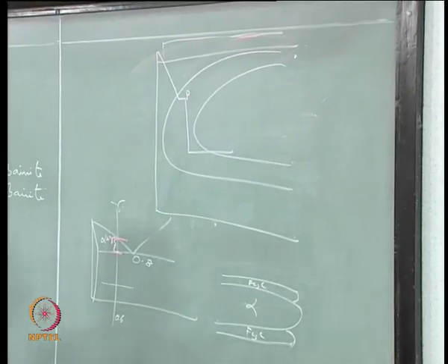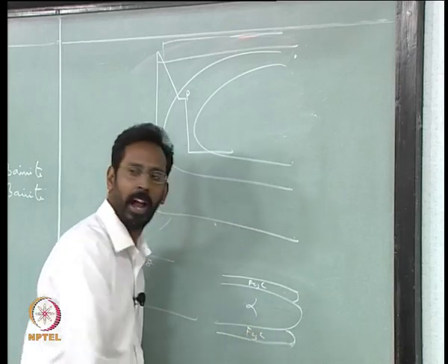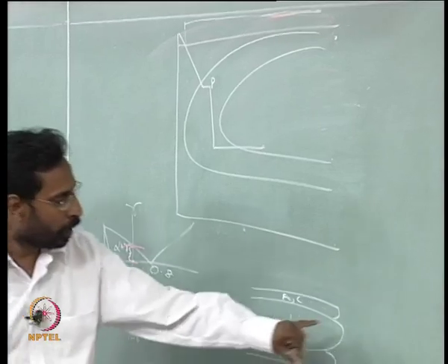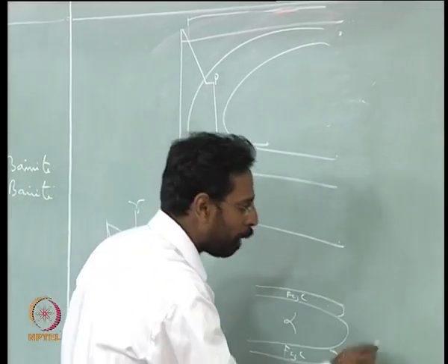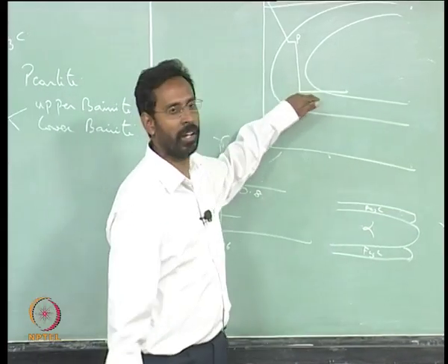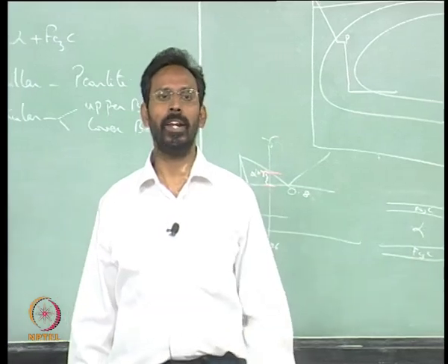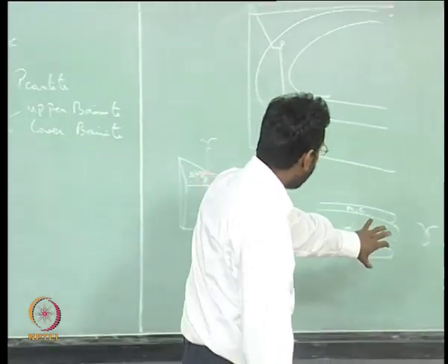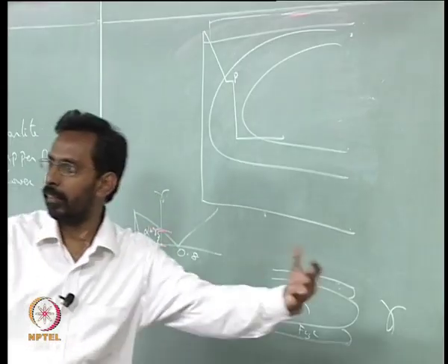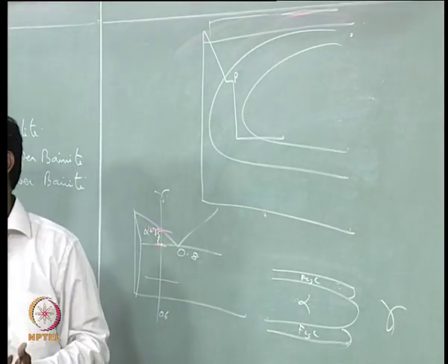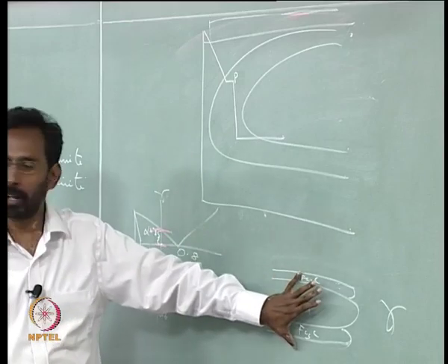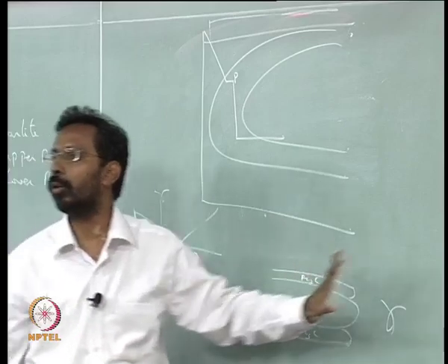So to start supplying carbon atoms to Fe3C and alpha, okay, the Fe3C needs more carbon atoms. So you need carbon atoms to diffuse from the gamma, which is here, into this. At this temperature that diffusion can be very difficult, because you need a longer diffusion, because from the whole of the gamma grain the atoms have to start moving, and because it is difficult at lower temperature, this pearlite whatever has formed will not grow much.